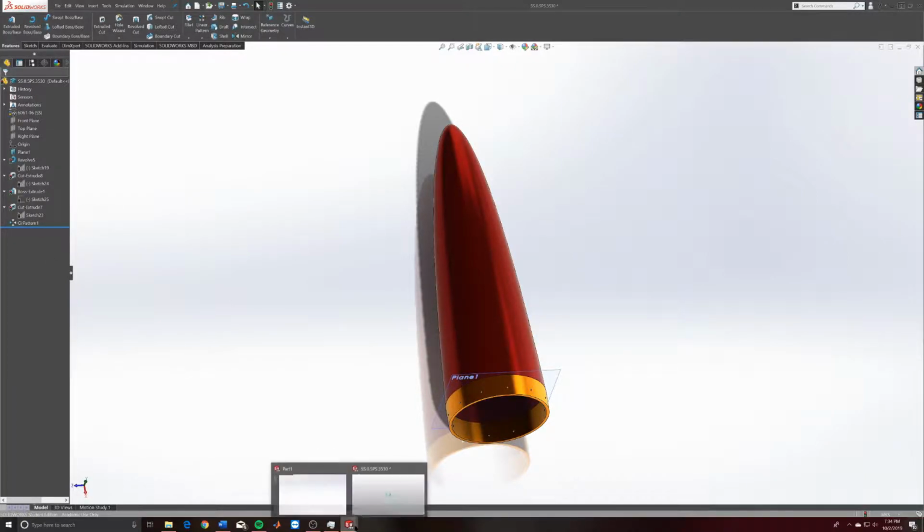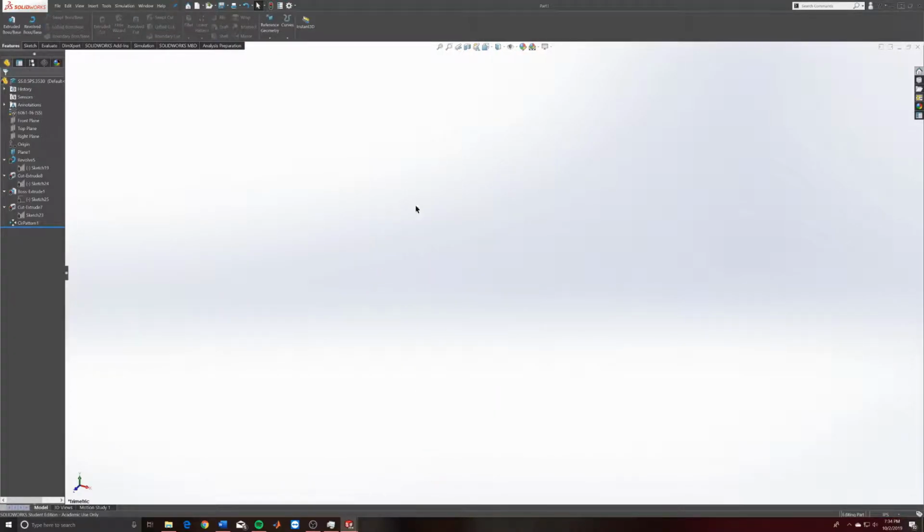So from here, let's go back to that empty sketch. You don't need to be distracted by a beautiful nose cone like that, but from here is where you're going to edit. In this window, all your edits will show up down here. These are your normal 3 isographic planes: front, top, and right. Then you have your origin point that you can also use as a reference when drawing. I highly recommend that you use drawings out of the origin. It makes it much easier to import into assemblies later on, and it's less of a nightmare. Just trust me.